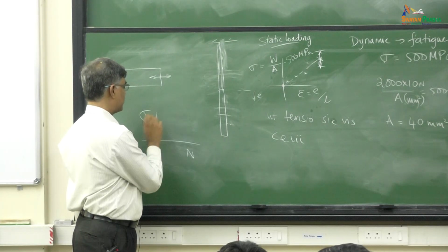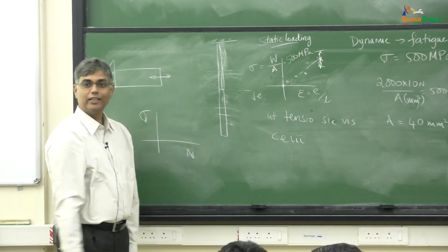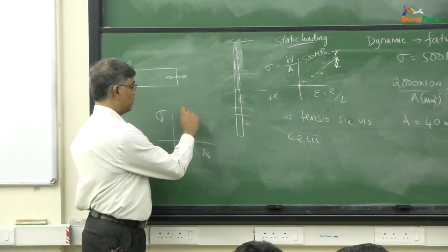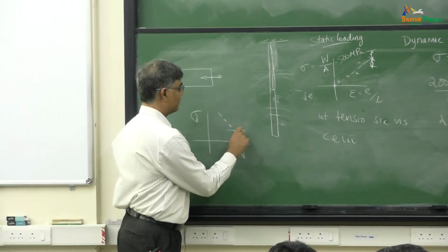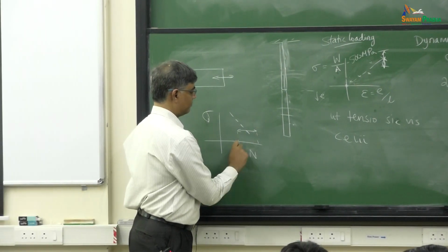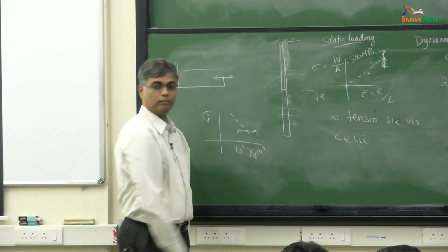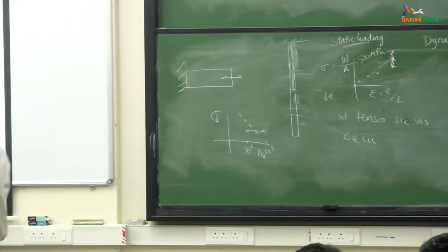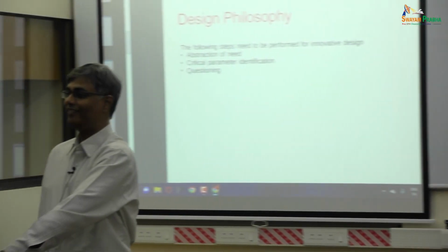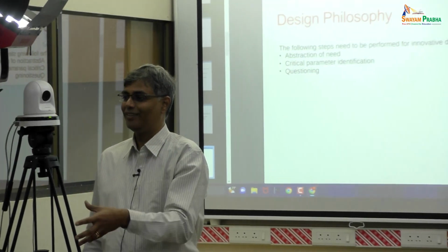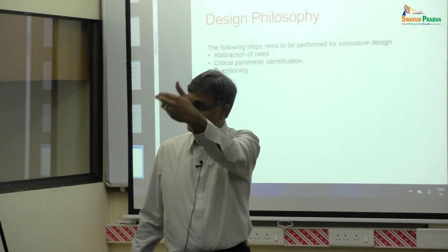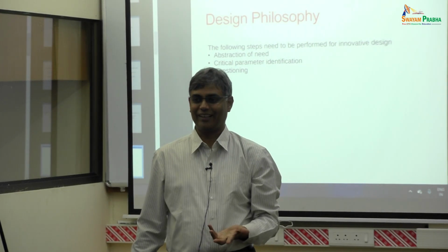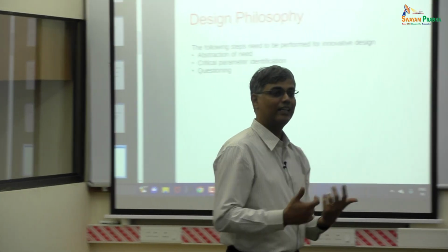If I look at the stress applied and the number of cycles to failure, we get a curve that looks like this if you do the experiments. Do you know the variation in that? It could be a factor of 10. At a given stress, a thing can fail in 1 million cycles, or it could even fail in 10 million cycles. Factor of 10. That means if you want it to be safe, you have to make it 20 times as thick, even for the worst case scenario for it not to fail. So that is the consequence of the current approaches.